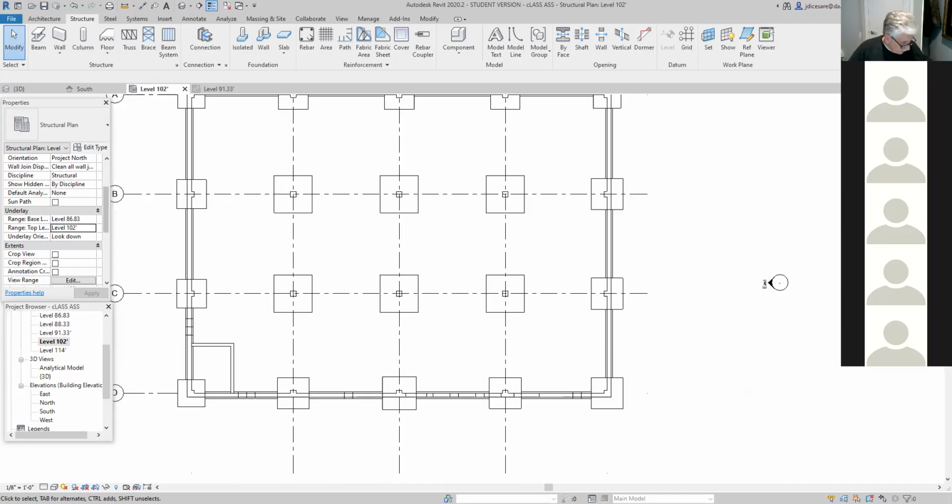But so for example, if I look at the drawing right now, if the wall is going to be going in somewhere around here, it's going to be going in like this, like this, and like that. That's where my wall is going in. Now from here to here, the bottom of this wall is going to be at 91.33.